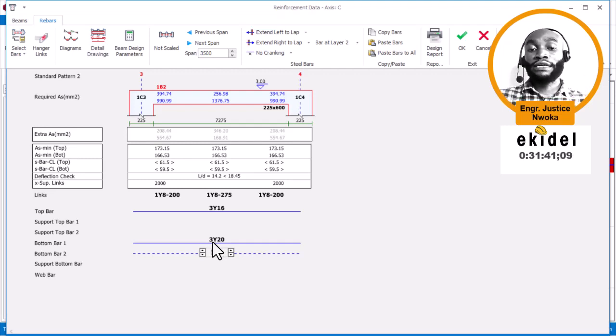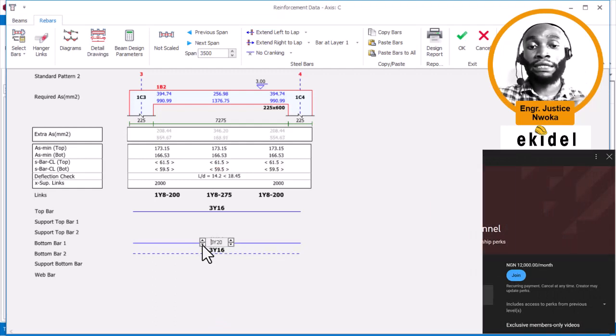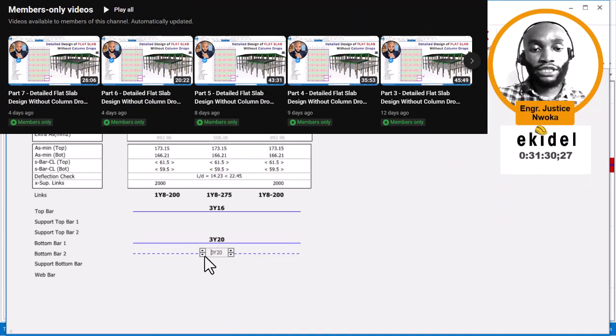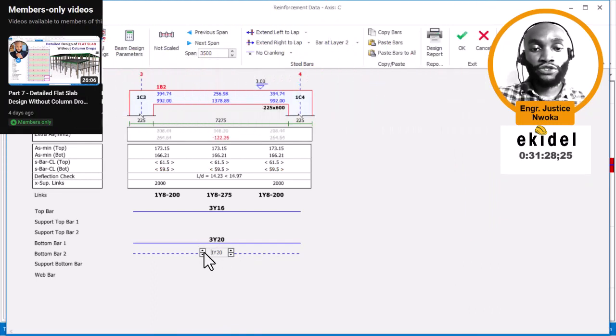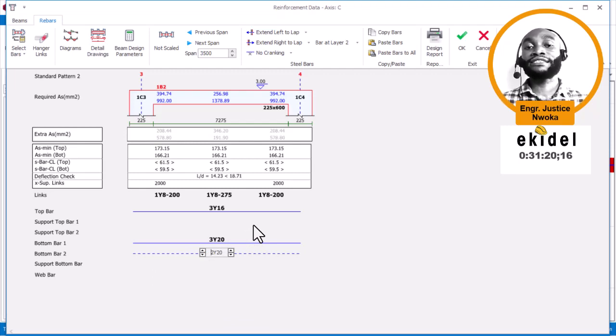Okay, that's fine. So you can see that right now they need a much larger number of bars at the bottom. Basically, if we are going to do it at Y20, let's check the number that is now needed here. Let's check, reduce. Okay, so you can see that at 4 it is failing. So at 5, so basically, sorry, it's 6. Basically this needs 6Y20. All right, 6Y20 is needed, against the one that was with the pin.